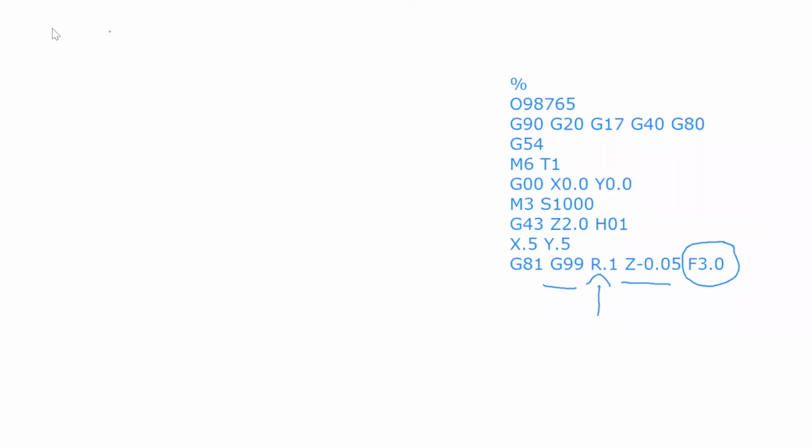How I got that number, and I will get you guys a formula worksheet, is inches per minute equals inches per rev times RPM.